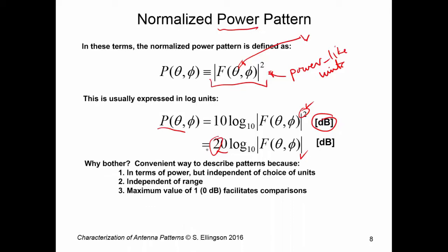So why bother with the power pattern? It's a convenient way to describe patterns for 3 reasons. First, it's in terms of power, but independent of the choice of units. Right? So we're talking about something which is proportional to power, but we don't have to say whether it's watts or milliwatts or microwatts or watts per meter squared or something like that. It's simply proportional to power.